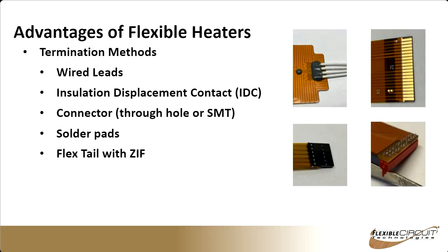You have multiple termination options available with flexible heaters. So, pretty much anything you can do with a flexible circuit or a traditional rigid PCB, you can do with a flexible heater. So this could be wired leads. If we look at the upper left image there, these are just wires that get soldered on. That particular example has potting over the leads to help protect them.